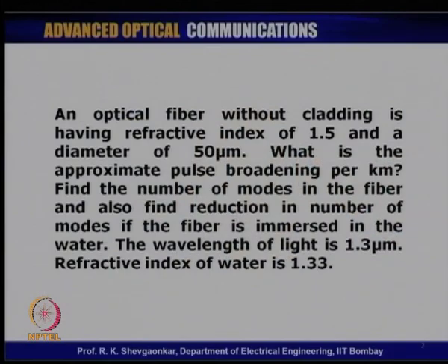The second thing which is asked here is how many modes are going to propagate on this optical fiber, and when the fiber is immersed inside the water, how many modes will be there. So, what is the reduction in the number of modes? We can see here, first of all, as we know approximately, since the fiber is multimode, the number of modes are approximately given by V square by 2. So, first we have to calculate what is the V number of the optical fiber,